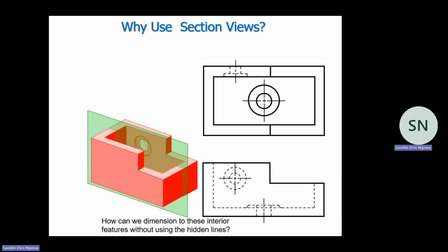So when we cut that block into two halves, the one we are going to remove, and the other is the one that we are going to look at. And then in an actual 2D drawing on the top view, you can see that the one highlighted in red there is how we indicate our cutting plane. And those arrows indicate the side that we are looking at, and the side the arrows are looking away from is the one that we are going to remove.